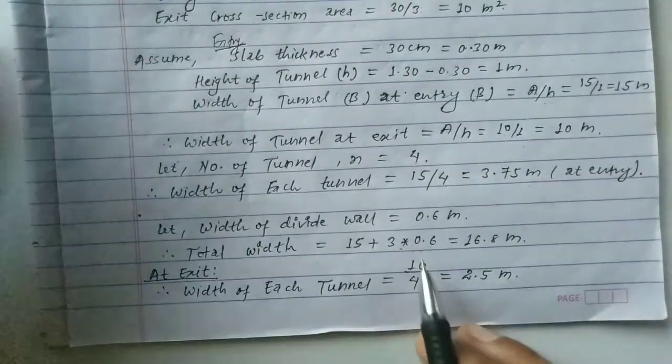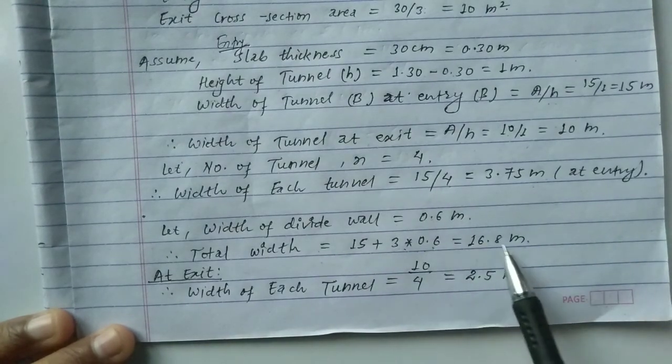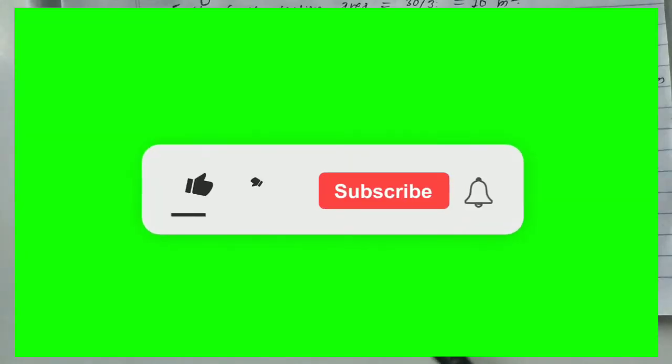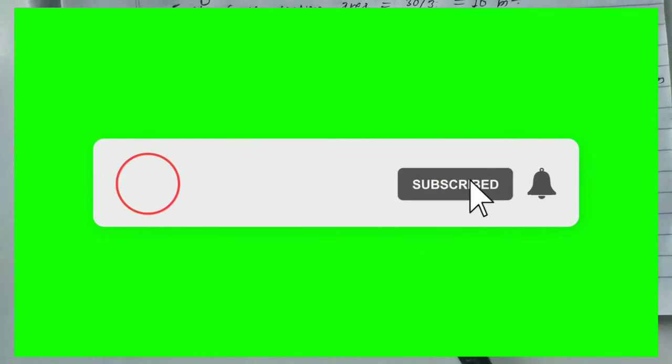In this video we have taken the number of tunnel equal to 4. That's why we have to multiply with n minus 1, that is 3. You can see here n minus 1 is 3, total width equal to 15 plus 3 into 0.6. Then it becomes 16.8. At exit, width of each tunnel equal to, we have to calculate for the single tunnel. We have total number of tunnel equal to 4, so we just divide this width of tunnel at exit, 10 meter, by 4. Then the width of each tunnel becomes 2.5.